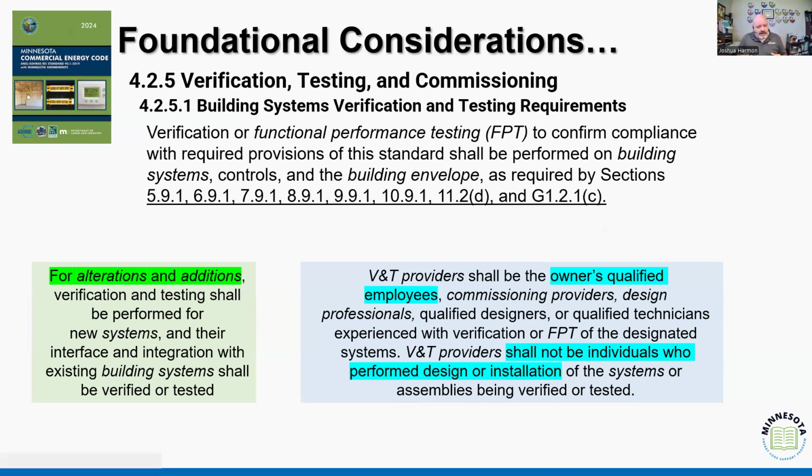I always go back to this concept that when I, as a mechanical inspector, inspect a new furnace or appliance, some piece of equipment that's been installed, I'm looking at the safe installation, right? I'm making sure that it's properly anchored, that it's properly connected to a fuel system, that it's properly wired.